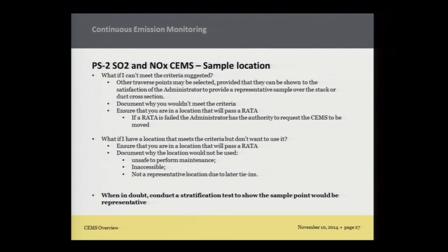So you're like, I don't want to put it there because I may have something of that pollutant coming in downstream of that. I mean, this would be a lot of times where you're looking at maybe like a flare line or something, and you're trying to figure out where to put a BTU analyzer or GC or something. Most likely on heaters and stuff, that's not a problem. Maybe an inlet-outlet control device, but a lot of times flares is where you would run into that.